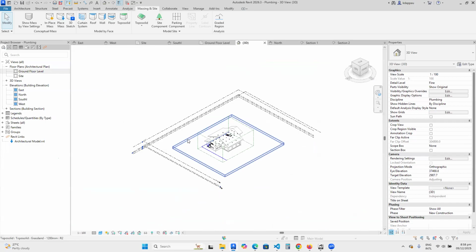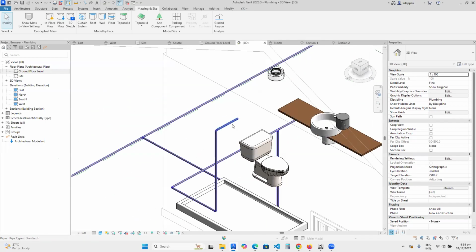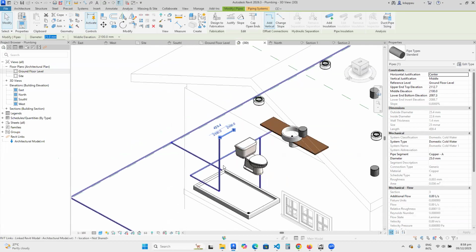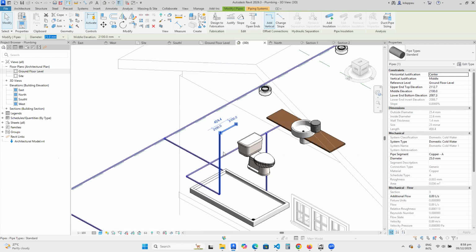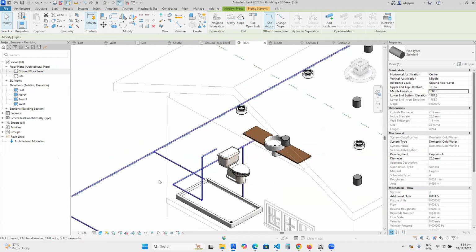Let's look at it from a different angle so you can see it. So this is a pipe. This height can be too high. It can be too low. That decision will come from the way you want to fix your shower. Or you can just select it, go to the properties, change it to a value you want. Let's say 1,800, if that's what will make sense. And if it is 1,800, then somebody who's taller than 1,800, that person's head will hit the shower. So it all boils down to design.